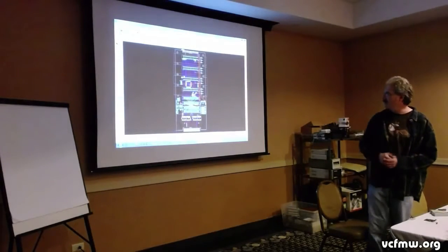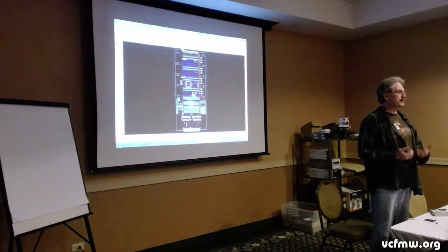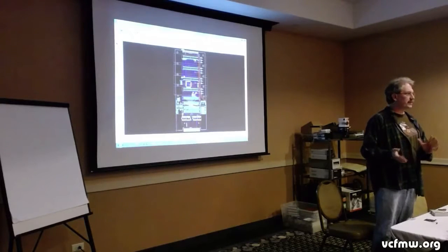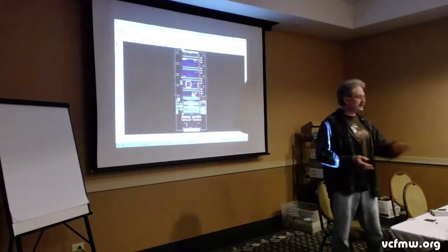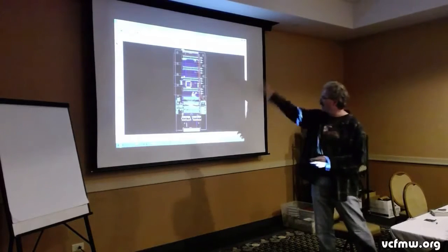So one of the things you want to start with is a schematic. Now remember, a CPLD is a programmable device, so you don't have to focus so much on how to use the device. You just need a footprint and the schematic version of it, and then you can start laying out the device.